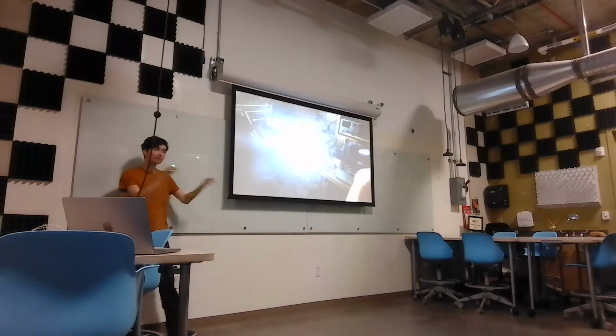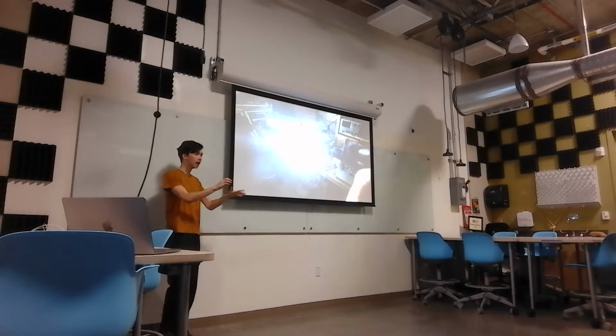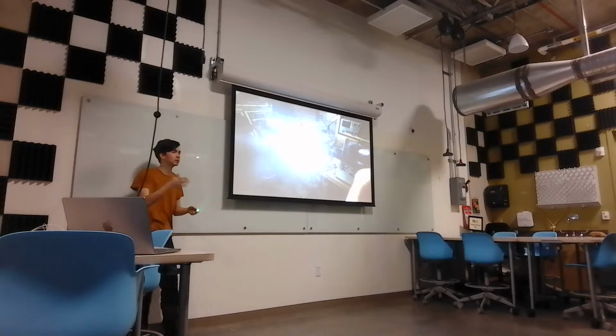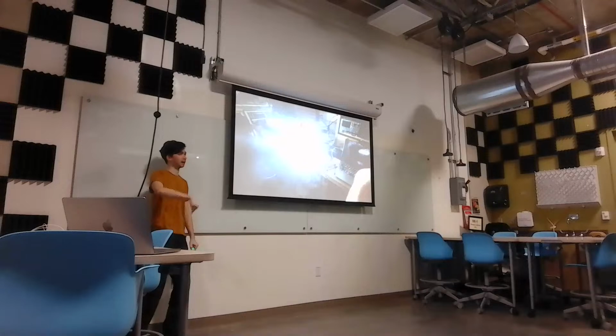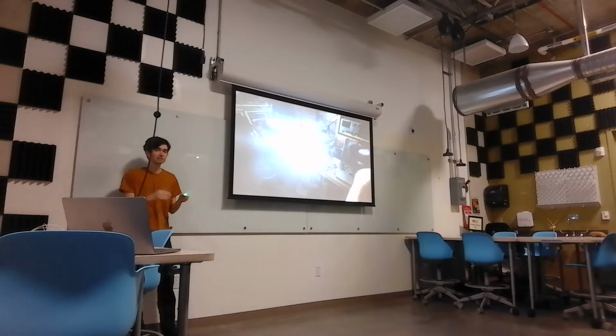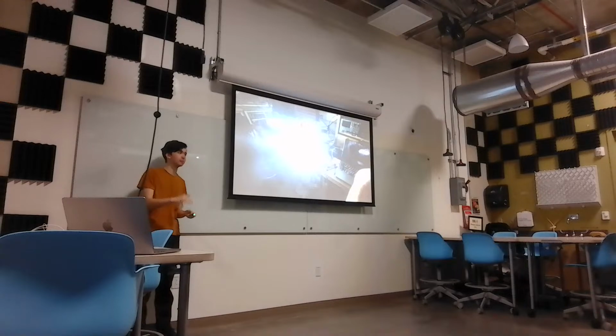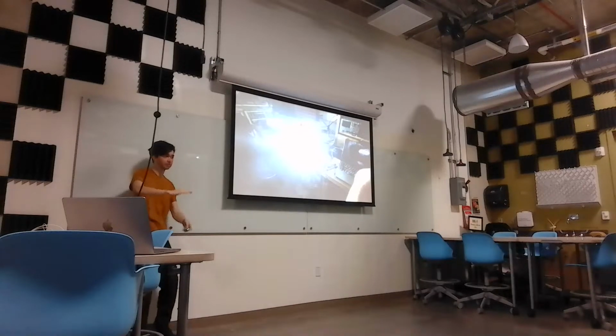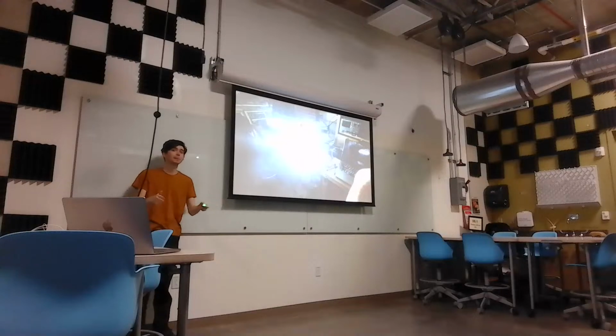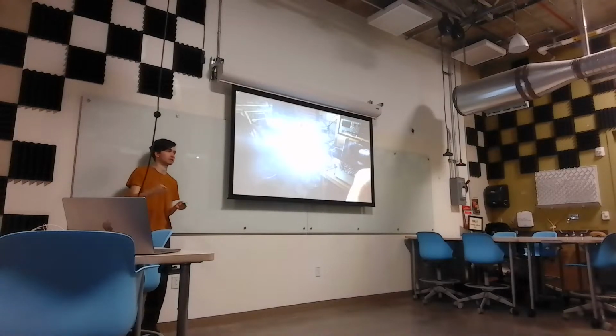So I don't know if you guys, that video actually really well showed what we're talking about, this whole PWM thing. The height of that waveform was our input power supply. And the goal of my board was to make it such that the average voltage on the output remains constant. So that's why when it got taller, it also got thinner. And then if you think about it, the area under that waveform was remaining constant, because that means the energy throughput is remaining constant. Does that make sense to everyone?